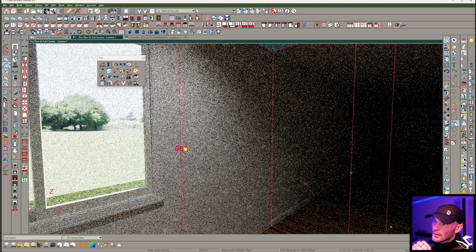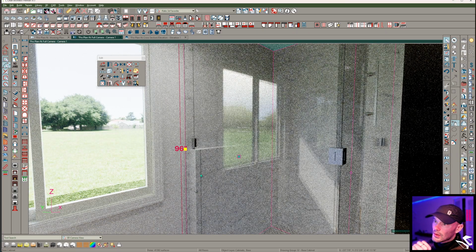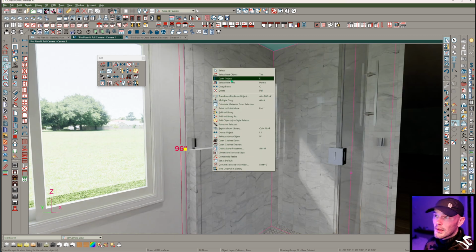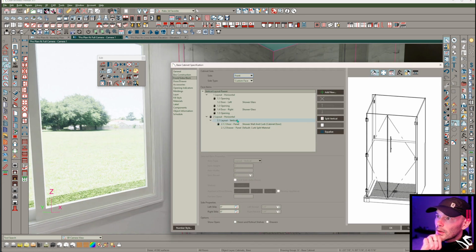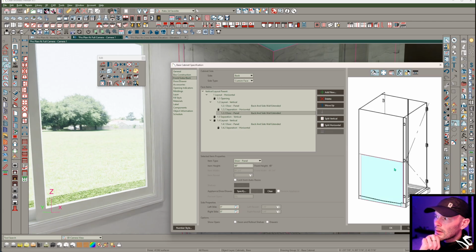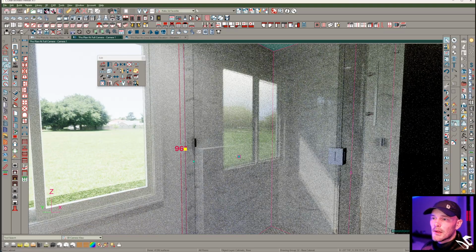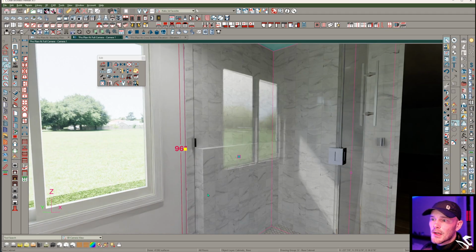And so now, when we go look at this, if I did that right, it should be that, yeah. Let me just cut this back a little bit more. This layout horizontal, we're going to say layout vertical on the back. We're going to say that this section is a little bit wider. It's layout vertical. Just call it 6 inches, something like that. And you'll see now, look at this. The backsplash is carrying through. The shelf is actually built to the inside of that glass wall. So you can see how this becomes dynamic.